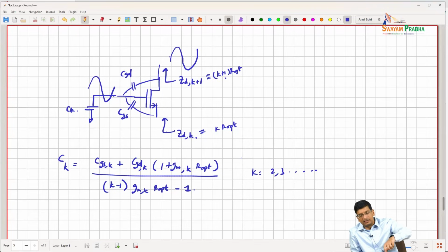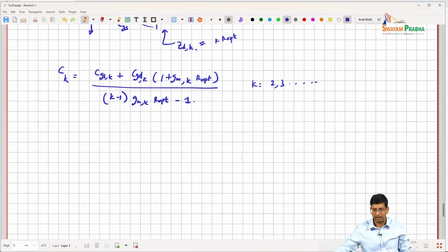You can bias this node based on the VDD distribution, right? So this kind of approach has been shown at millimeter wave to be able to work well to create high output power without the need for large transformation ratios, which are difficult to implement at millimeter wave, right?